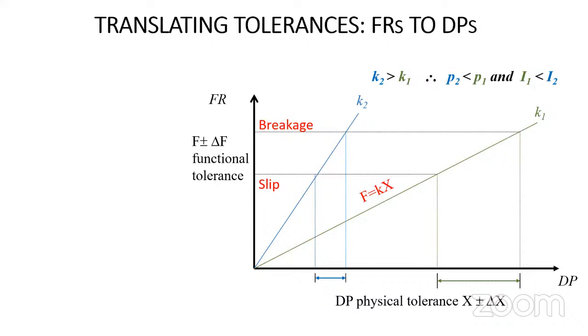I want a really quick response. I want to lock that thing in. But if you think about temperature change, all kinds of things can change the size of that cam surface that I was trying to represent on the previous slide. Tolerance I can get. Variation in manufacturing. I want a bigger tolerance. So I would like the softer spring.